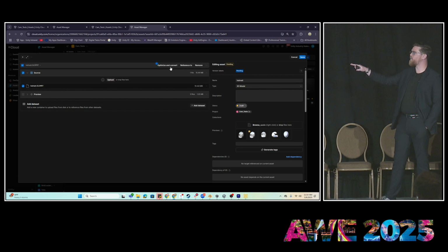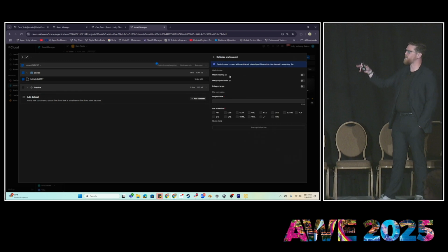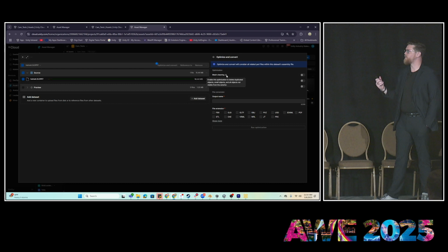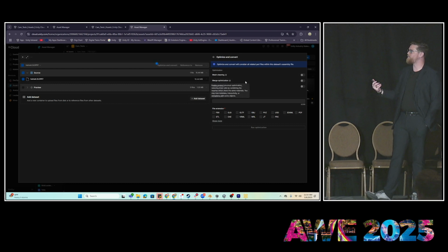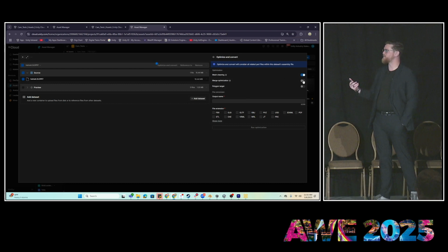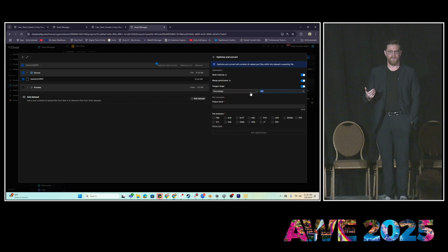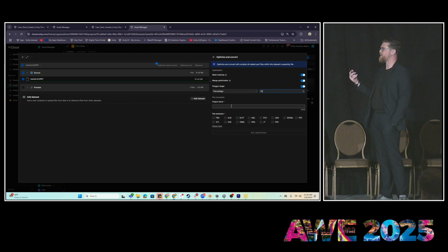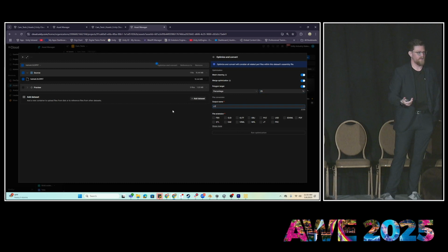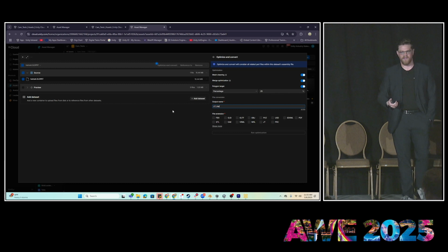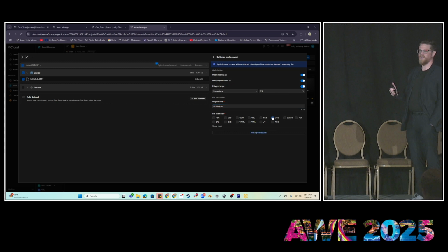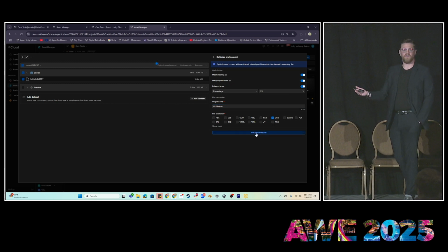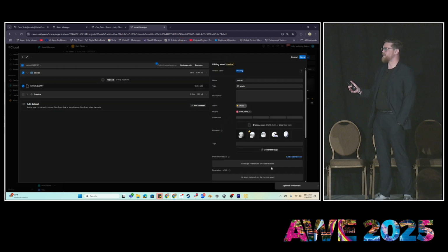Now before we look at what just came out of that process, let's run an optimize and convert. We're going to go ahead and turn on mesh cleaning and the merge optimization as well as a poly target. We're going to specify a poly target of, let's say, 25% and name this that we want it to be a low poly asset. We can then specify, let's say we want to do a USDZ file or something comparable. Now we can hit run.